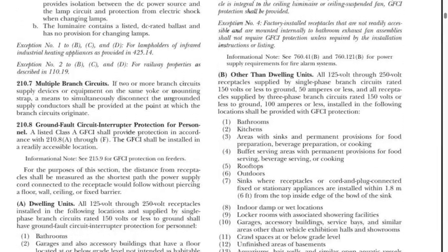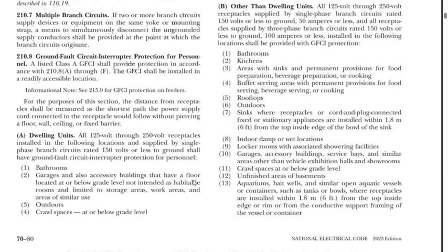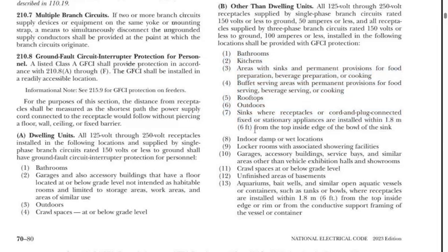So that's all. And these are all the locations where GFCIs have to be used in those two different style occupancies. In houses, in all of these ones. In other style occupancies, then you'll have different things. So all of these. Whoops. Hard to highlight with this PDF sometimes.